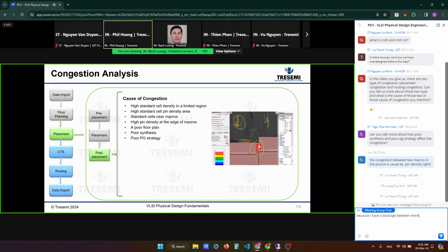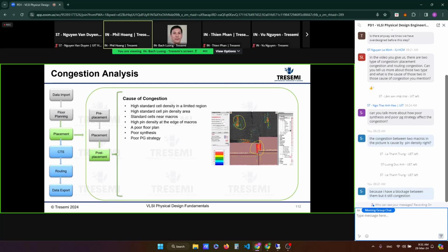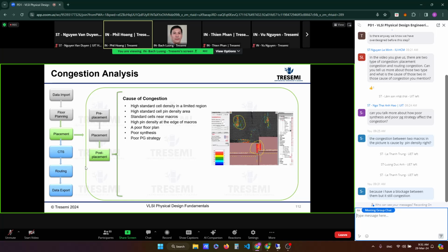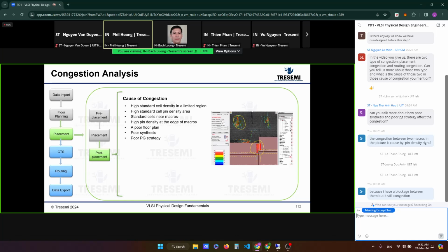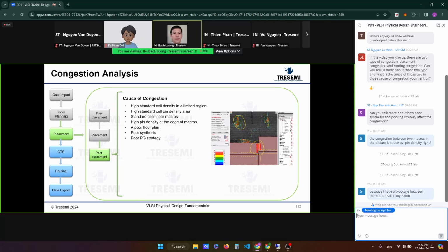And also, at the distance, right, is pin density right there. Yeah. But also to help with congestion, you can block the cell placement. If the cells are placed in those chimneys, we call them chimneys, that will magnify the congestion. So there are constraints that you can put in, say, don't put anything except buffers in there, just to minimize the cells being placed in those chimneys, right? But at the distance, these look like pin density problems, not cell utilization. They look like pin density.